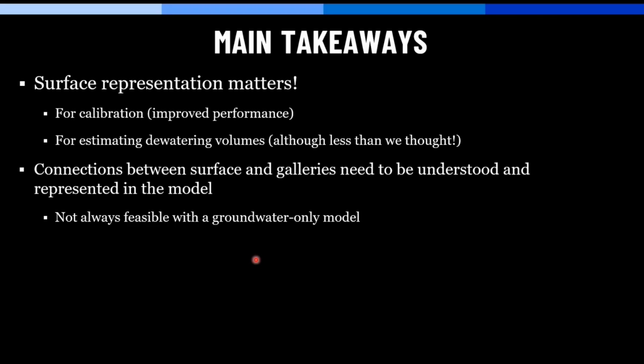We also found that it's probably important for estimating dewatering, but maybe isn't as important as we thought it was, or rather it's not necessarily important to the quantity, but to understanding the mechanism by which water gets into those galleries themselves. So in this case, understanding the connections between these large surface water bodies and the galleries through these potential fault systems is probably what is going to drive those dewatering values, and is something that the owners of this property probably need to pay more attention to or get more information on as they plan dewatering efforts.